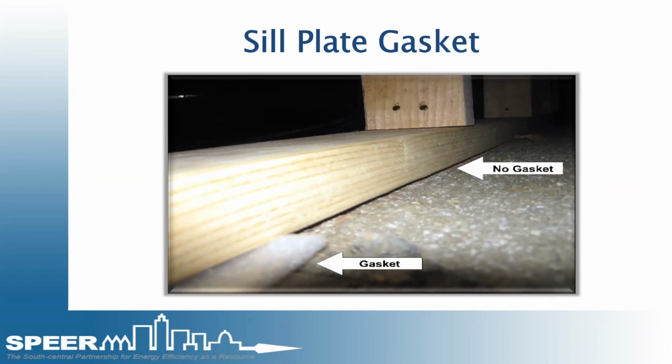The seal gasket, I know this is mostly used in construction as a moisture stop. It stops wicking from a wet concrete to wick up through the base plate. But the seal gasket also in place stops air infiltration from underneath the base plate. Wood is not always perfect. Concrete is rarely ever perfect.